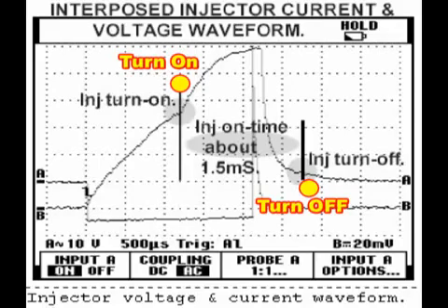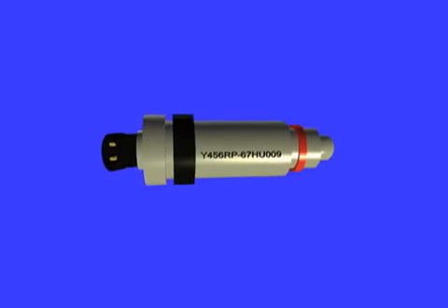If the spring is weak, the injector waveform closed hump will show up late. If the pintle channel is clogged, the open waveform current hump will also show up on the waveform. The oscilloscope test is the fastest way to determine a possible injector problem. Use the ADP scope 1 to capture the waveform and analyze it. Don't forget to finalize your measurements with an actual manual injector leak-down procedure.